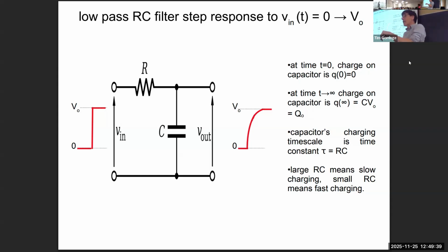Once we've got the difference equations for the low pass, high pass RC filters, we'll see that they essentially are the recursion relations that define the digital version of those filters. So we're learning how to go from a current knowledge of analog RC filtering to an algorithm for digital low pass, high pass filtering.